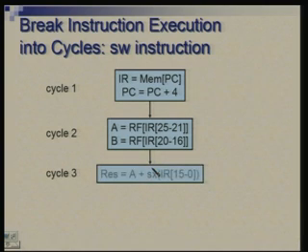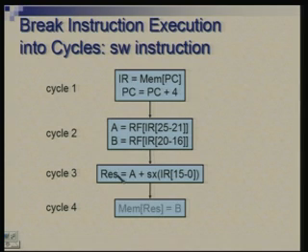In the next cycle, we calculate the address, okay, by adding offset coming from bit 0 to 15 of instruction with sign extension to A, and this value is temporarily kept in this register called result. The last cycle will see an access to memory, where contents of RES will be used as an address and the data to be written into memory is B and memory write is performed. So, once again we require 4 cycles.